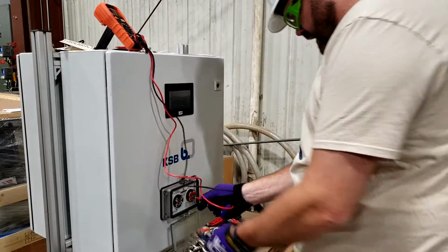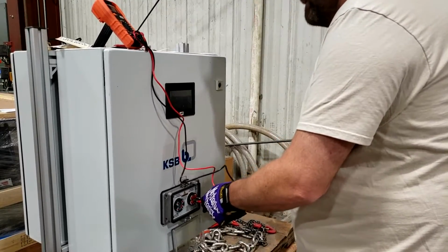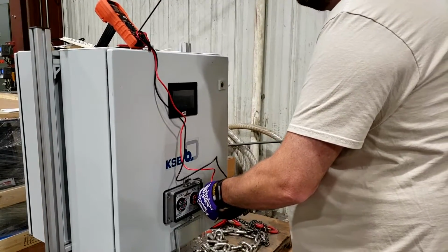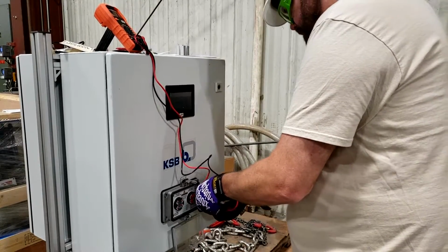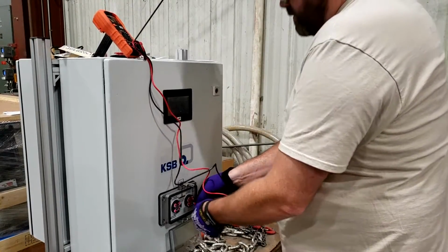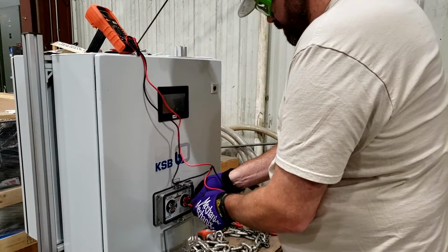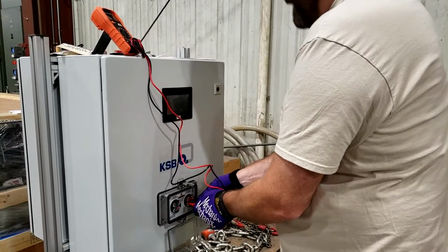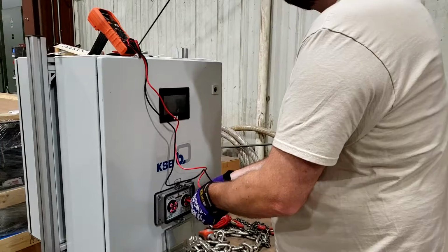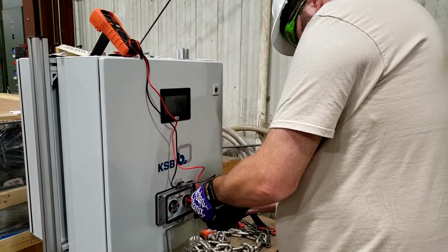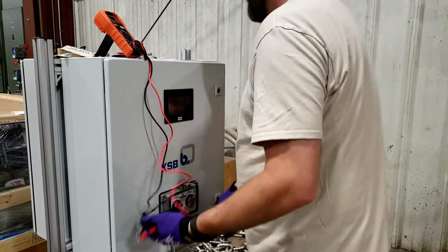Using the multimeter, we will begin troubleshooting utilizing the voltage test points on the voltage test station. We will perform the following tests: ground to leg 1, ground to leg 2, ground to leg 3, leg 1 to leg 2, leg 1 to leg 3, and leg 2 to leg 3. While doing each test, we'll be communicating out loud that the voltage is okay for the test that we were doing at that time. Once we have completed all 6 tests, we will close and latch the door and communicate out loud that all voltage has been verified good.